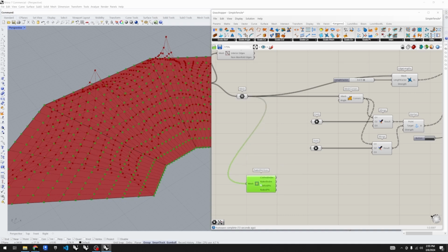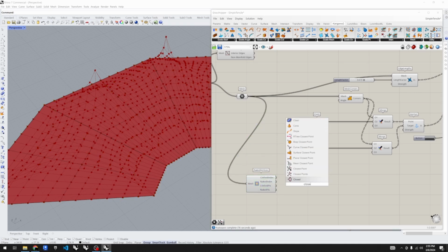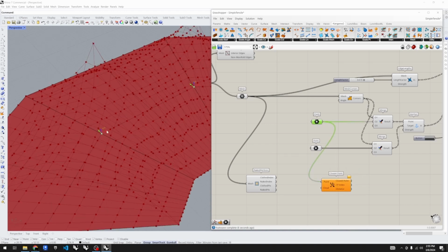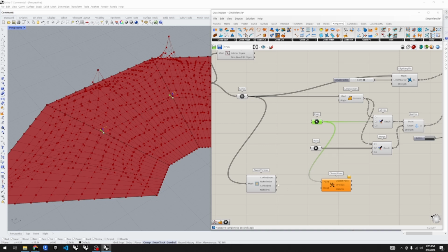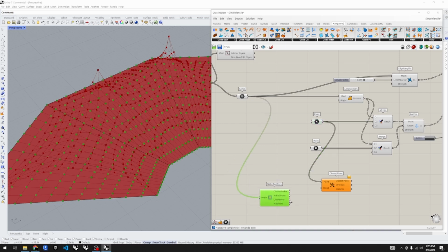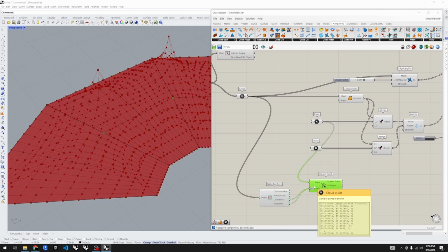So what we'll do is take the closest point, and the point we want to use is our anchors over here. So there's our points that we're going to use, these ones. If we move them, these are the ones that the closest point is acting on. And then for our cloud of points, we're going to bring in both the clothed points and the naked points, and we'll just flatten that all down so it's in one nice closed list.